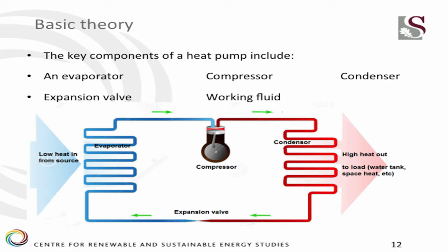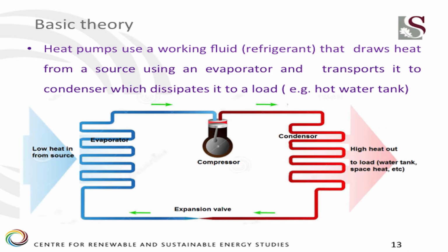The easiest way to understand this system is by understanding that when liquids evaporate, they require energy to evaporate. So they pick up energy. And when they condense, they give up that energy. So at your source, you must evaporate, use an evaporator to pick up that energy, compress the fluid that you are using, and then condense into liquid, losing back the energy.